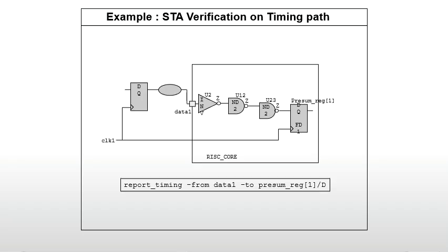As shown in subsequent slides, the STA tool extracts data on path information, path delay, the AAT, path requirements, the RAT, and the summary that presents the computed slack, indicating the violation status. Let us go through each of the timing verification processing steps involved.